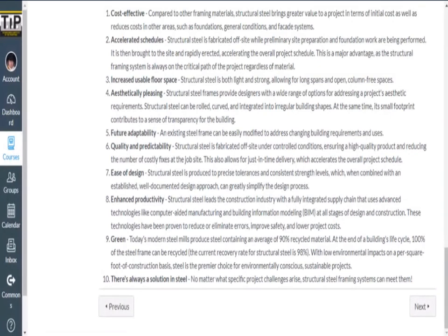If the material is weak, then you need to compensate for it by providing larger sections. And larger sections will lead to larger volumes, which would lead to larger masses. That's why if you want a lighter but stronger structure, you can use structural steel. And at the same time, you can use structural steel for longer beam spans, because it is stronger, so deflections will be less than that of concrete.